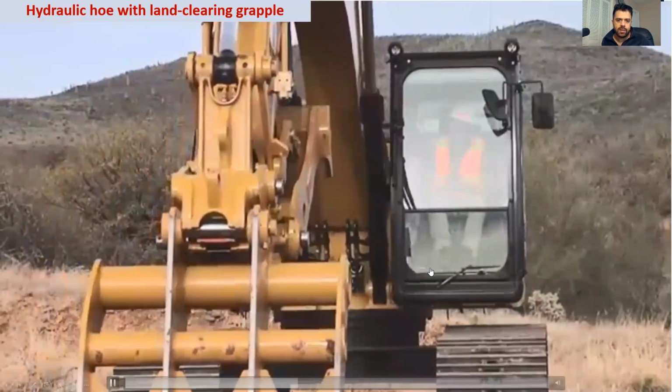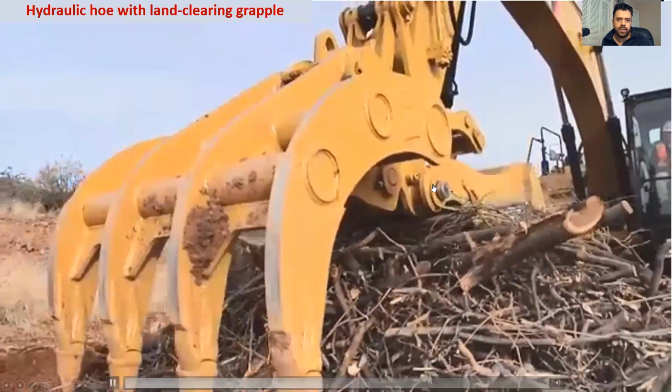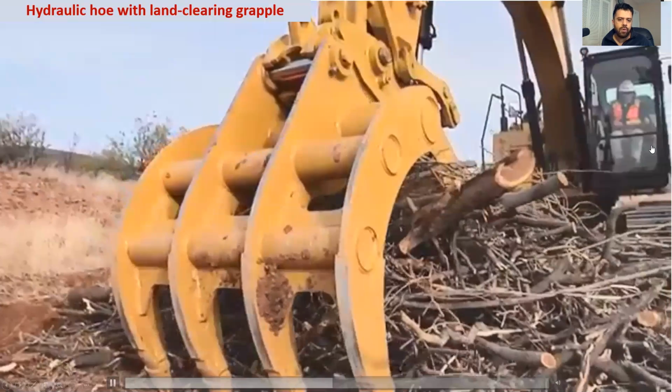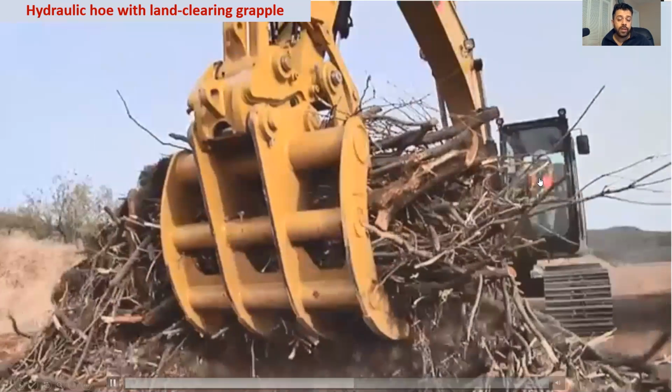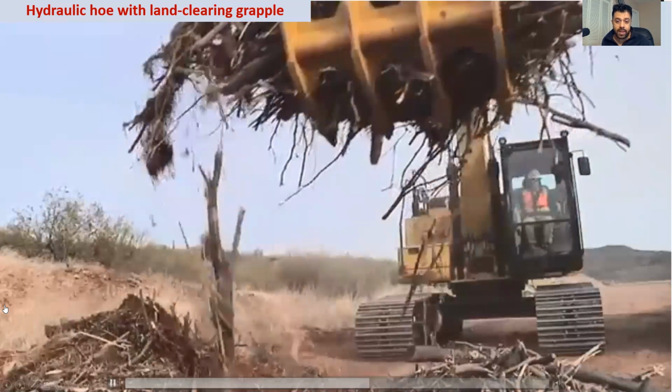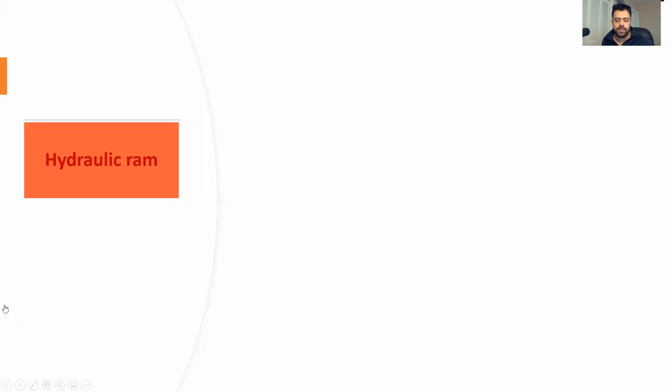So like I said, one main, easy way to tell apart a hoe and a hydraulic excavator is that a hydraulic excavator can rotate. I have seen that people in the industry use them interchangeably sometimes by mistake. Maybe pronouncing hydraulic excavator is more difficult than saying hoe, so most of the time they just use backhoe, even for hydraulic excavator, but that is not correct.